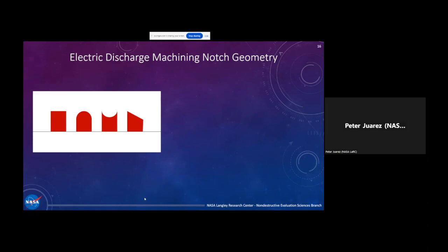And so when they processed the data, they basically made POD curves for a bunch of different scenarios: if it has a concave or convex top, if it's perfectly rectangular, and what is the probability of detection given that. And then ultimately, in practice, you would just go with the most conservative POD curve that came out of that. But we can do a little bit better.